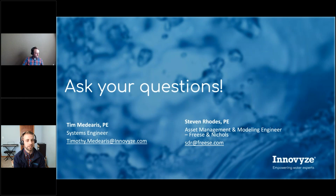Gotcha. And then second question, have you tried running this model or any of the models with water quality parameters as well? I haven't, no. I want to. I think that'd be kind of cool to do, just to see how that works out. Yeah, next time. We did get an explanation from Bob chiming in. Maybe at that 20 cores you hit some point where it starts to slow down the simulation because there are so many cores, core-to-core communication, talking to each other. So maybe that's the threshold you hit there.